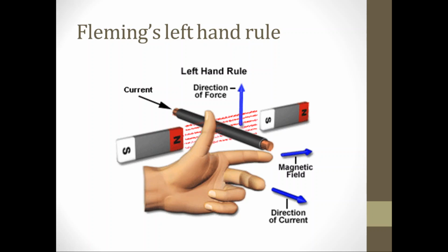So it means that there is no way for the DC motor to vary the strength of the magnetism, because unlike with the electromagnet, where the strength of the magnetism can be varied by varying the current flowing into the coil, in a permanent magnet the strength of the magnetism is fixed or constant.